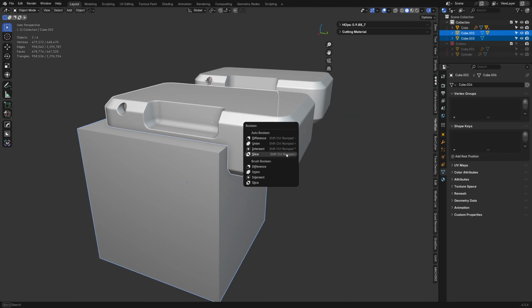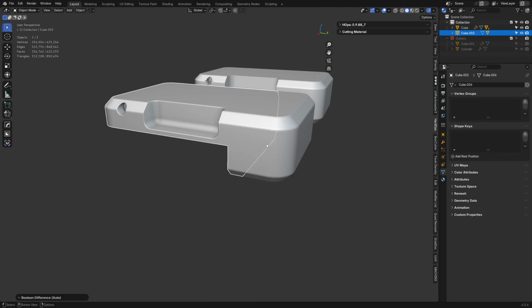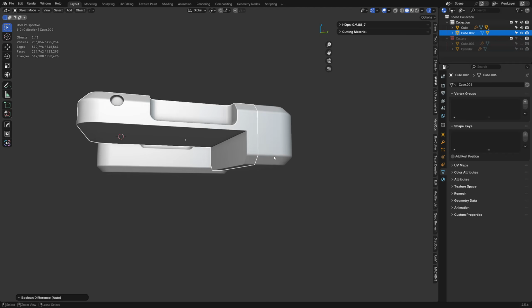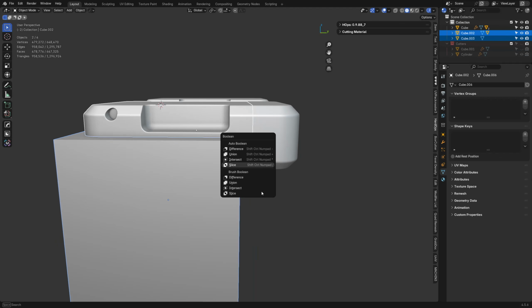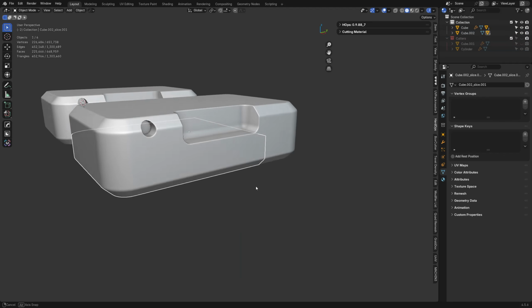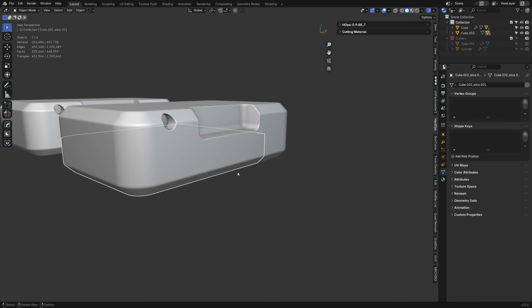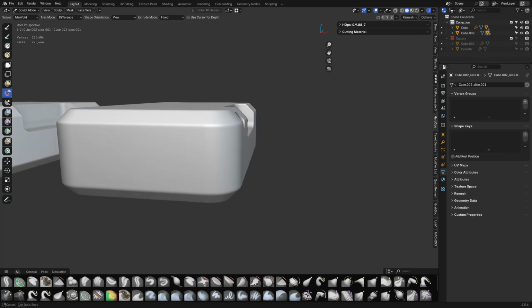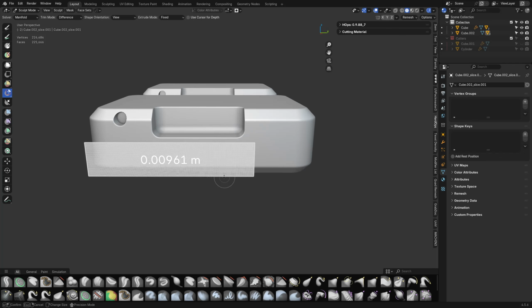So we can get in here, Control Shift B. We can do auto Boolean difference or use a shortcut. I'm going to use a shortcut from here on out for those ones. So I can subtract that, or we could slice it, right? If I'm doing slice, I'll still see that coming up because I just prefer that. But basically, we can do something like this. We can go back to sculpt mode. We can hit R. And you can see we can change the size, remesh it.